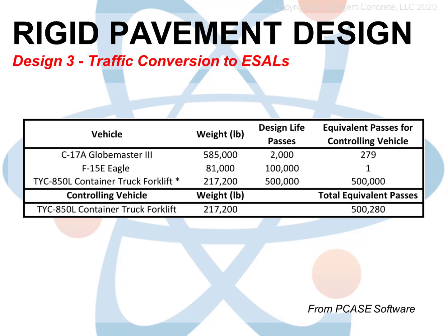That type of vehicle has 4 big tires per axle, each with a maximum load of 4,500 pounds. 4 times 4,500 equals 18,000, and a tire pressure of about 100 psi maximum. Airfields will have traffic with dramatically different loading cases, such as the F-15, which carries most of its weight on the main gear. So one single individual tire will carry 30 to 35,000 pounds or more, with tire pressures of